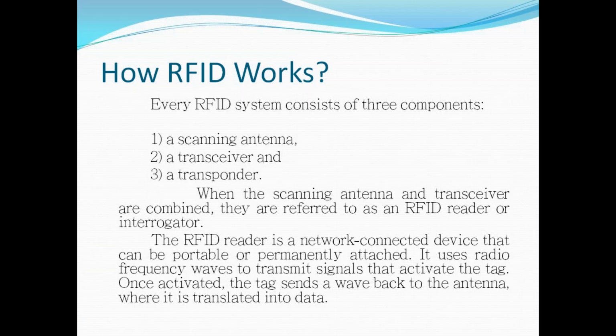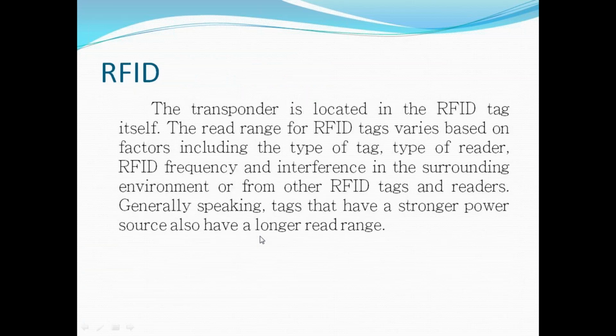The first 10 bytes represent the identification, that is the unique ID of that card, and the last two characters, or 2 bytes, represent the checksum. That means whether data has been transmitted properly or not. So whenever we have to read a card properly, we always have to read the 12 bytes, where the first 10 bytes represent the actual identification number of the card. Now, a few things I'll skip because I'll try to implement it practically directly.